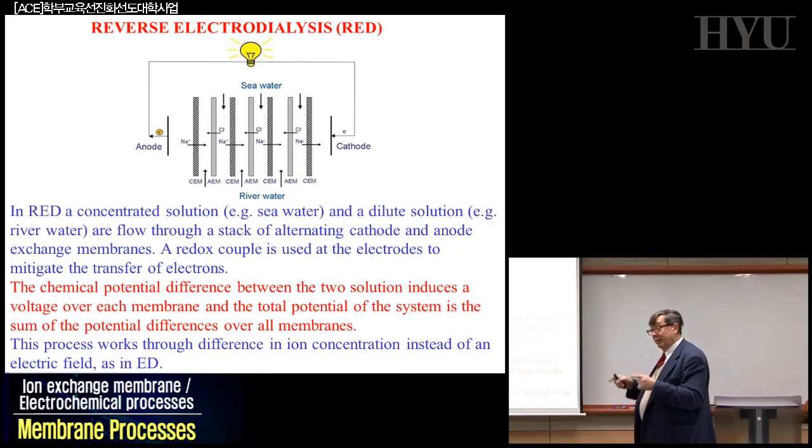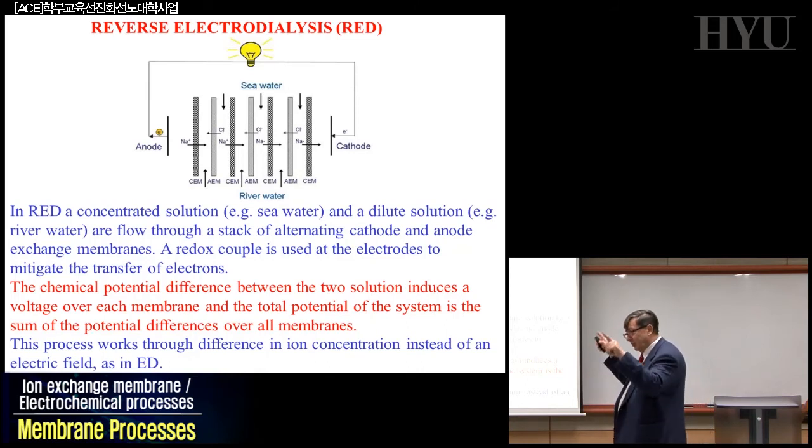And we learned before that 6 molar can be too high for Donnan exclusion. So your transport number is no more 1; it can go down. So you have to produce better membranes that can operate in such extreme conditions, and that's not so obvious. Plus, you have to control all the different additional resistances: concentration polarization, ohmic polarization. Here in this case also interfacial phenomena, what is called overpotential. Overpotential can reduce the capability to oxidize or reduce your ions, etc. So all these phenomena together make the system quite interesting but quite complicated.